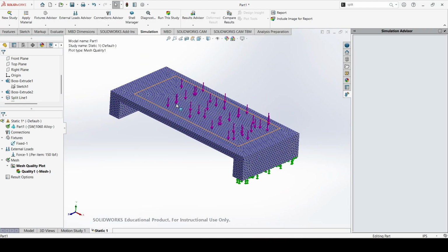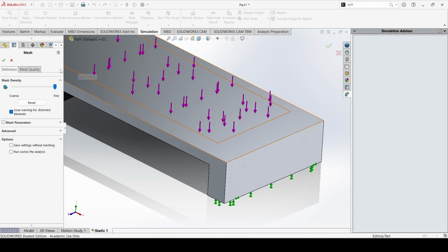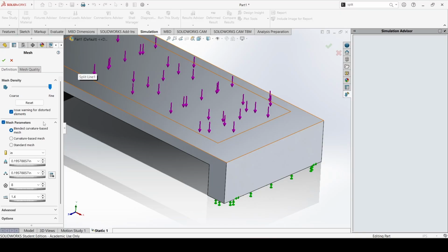Obviously, it's not perfectly accurate because these little mesh sections, these polygons, aren't infinitely small, but there are limitations on this. So if you go into advanced and Jacobian points, you might learn about Jacobians in Calc 3. Basically, it changes one section or one coordinate system into another.